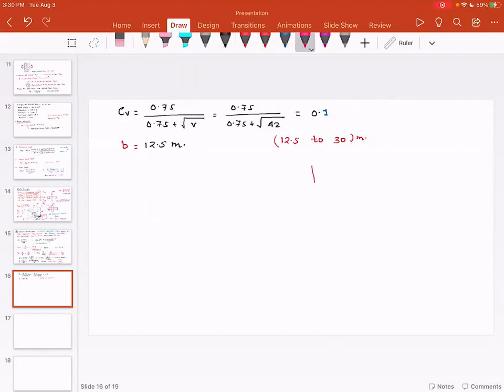Finally, what you want is your gear to have a certain proportion with respect to the radius. So this is the face width B, and say this is the diameter. The diameter of the gear is number of teeth multiplied by module, and B is some constant K multiplied by module.